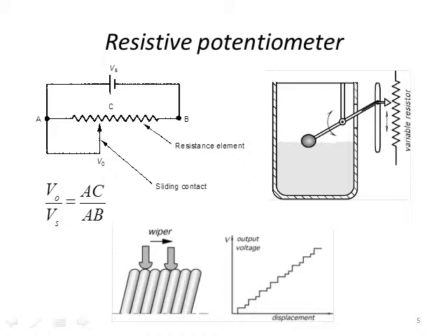However, you can see that typically with a potentiometer, we don't have a smooth transition in the output voltage as we move in displacement. We have little stair steps, as we see in the lower right-hand figure. And this is primarily due to the wiper fingers having a finite size. And as they move across the core of the potentiometer, it's difficult to make a linear and perfect transition between the core windings.